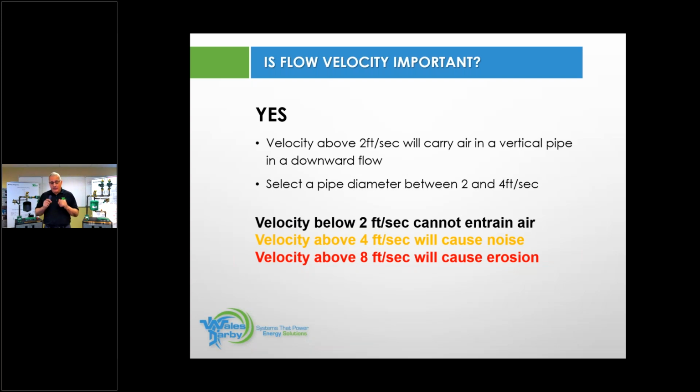All right. I'll give you a quick example. I was talking to a gentleman yesterday. He knew that he was going to have a problem on a radiant job that he inherited. And he said, the 007 is going to be too small head-wise. What should I use? I did the calculations, and he ended up needing a 009 for a very small bathroom. And he was using 5/16 in mud and feeding the manifold for that bathroom with 1/2 inch. Everything he inherited, he told me. Using a 009 in that instance would work, but you really don't want to do that. So he's going to re-engineer the job. We're going to see maybe we could do that as floor warming.